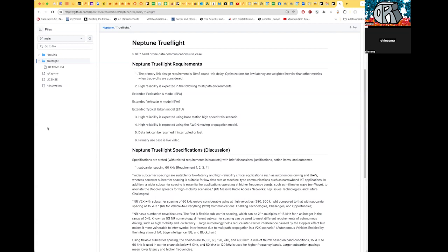There's other delays in the equipment, but our round trip delay, if we were going to propose 10 milliseconds round trip delay for the RF side, the feedback that I got for this requirement so far is that it actually should be closer to 4 milliseconds round trip delay and not 10. There could be other things contributing that we have no control over.